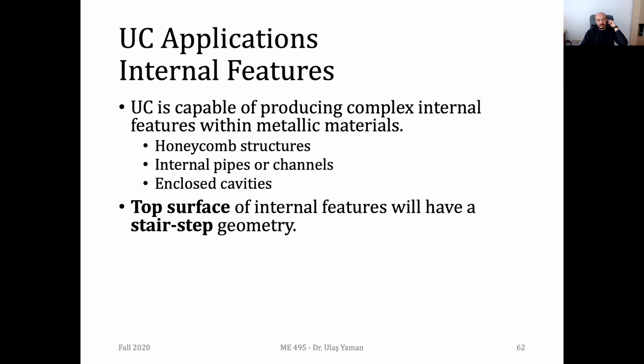We have another important issue. The top surface of these internal features will have stair-step geometry. If you remember, with ultrasonic consolidation in the previous slides, we said that we can eliminate the staircase problem. But right now we are stating that the top surface of these internal features will have a staircase effect.